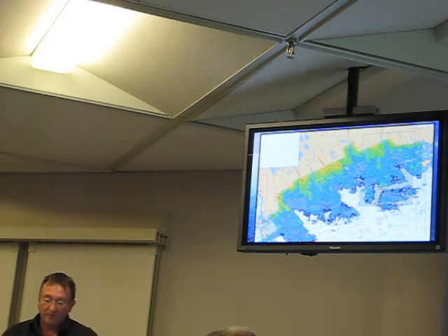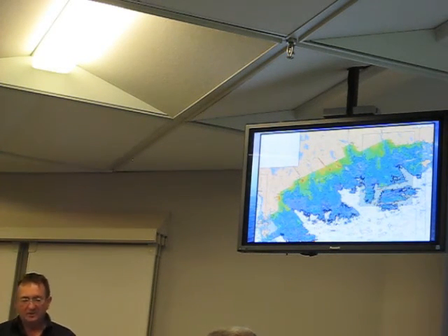And so now we're going back. We've done what's outlined here in gray, and these boxes are gaps. We took the LiDAR data, looked at all of our historical existing data, identified gaps or holes, and now we'll go back with the multi-beam acoustic systems and fill in the holes. And at the same time, we'll ground truth the LiDAR.